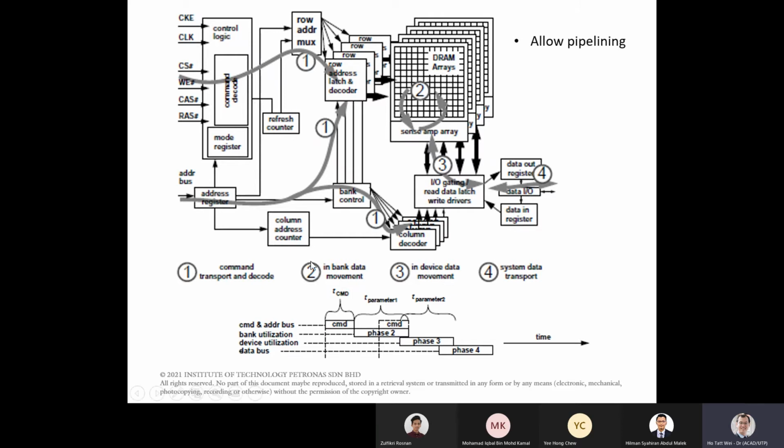Okay, so this is an example of a read cycle. So first you do this command. After you put the command, you have to wait a certain amount of time. There's a certain amount of time after the command decode is done. Over this time, it will go to phase 2 where it's actually accessing the DRAM arrays. It's going to do the pre-charge. Then the pre-charge is already done. You always do the pre-charge at the end of any command, right? That's what you always do.